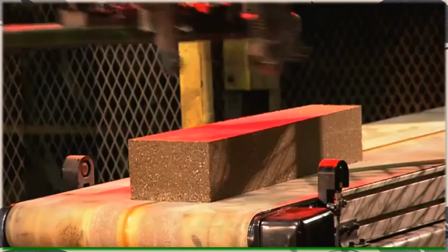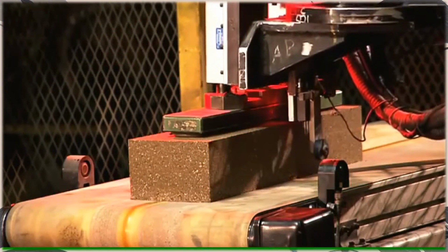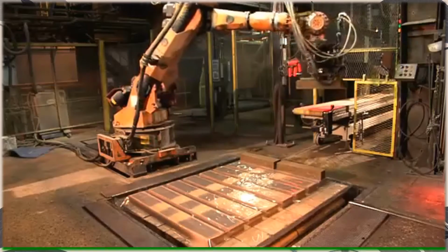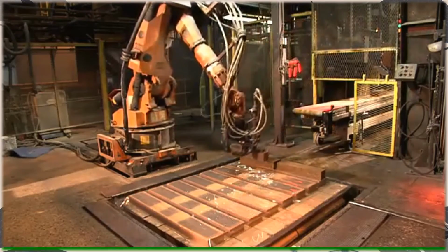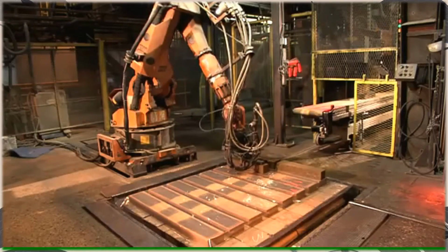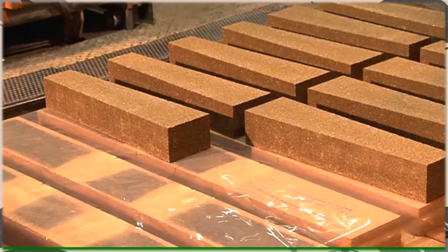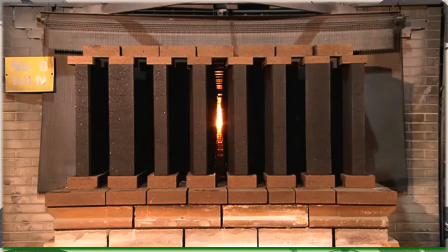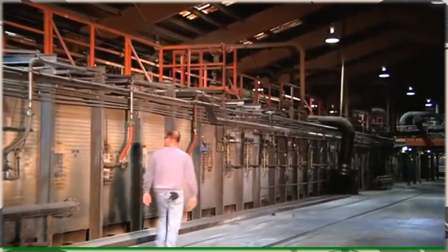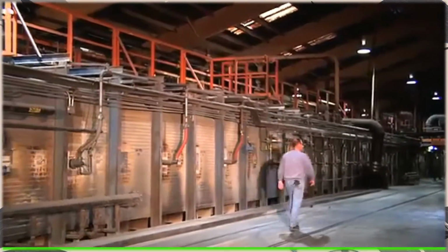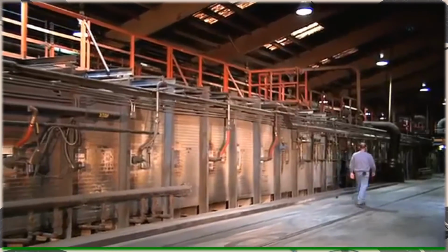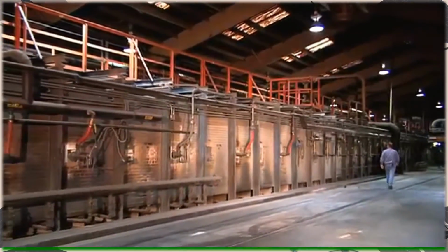After they are pressed and formed, most bricks and shapes are then subjected to high temperatures over hours or even days to heat treat the materials and complete the necessary physical and chemical reactions needed in a finished refractory product. Heat treatment is done in large industrial furnaces and ovens, usually called kilns, which may be designed to operate continuously or intermittently. Tunnel kilns can be hundreds of feet long and hold dozens of cars. This ensures a continuous process and the efficient use of energy.